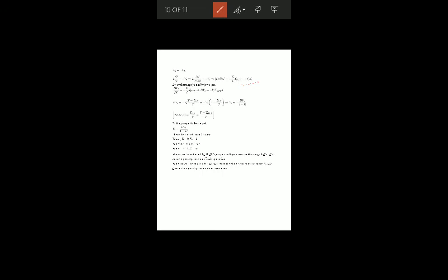Now V naught will be d Vs; we put f L on this side, L will cancel out, and rearranging the terms we finally get V naught equal to this expression. It is very simple, just rearrange the terms, where d is T on by T.